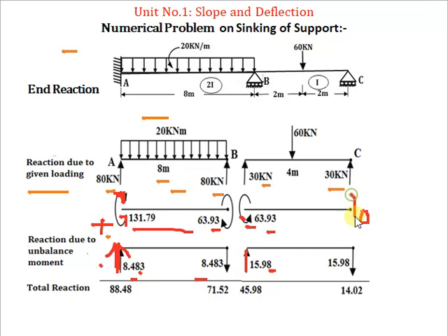So here the moment should be in a clockwise direction to balance this one. So show the arrow up, so when it rotates, it will get added here and create the moment in a clockwise direction. Now at the far end, you have to show the same magnitude, but the arrow you have to make in the opposite direction, that means in a downward direction.